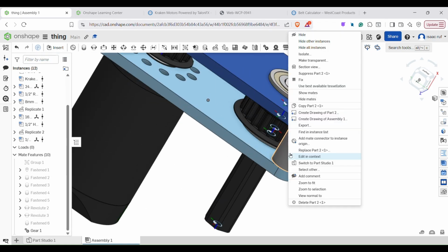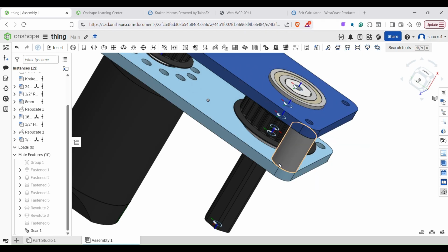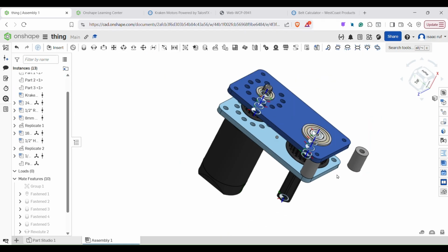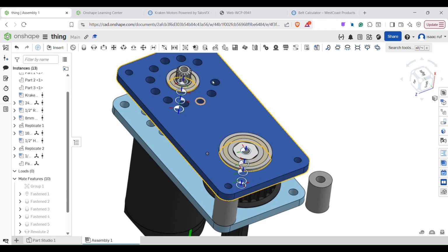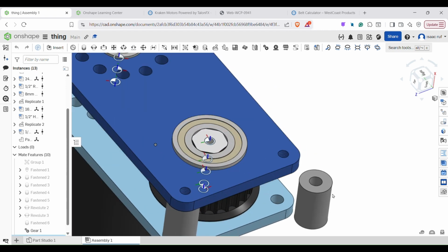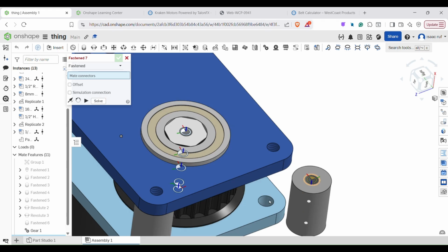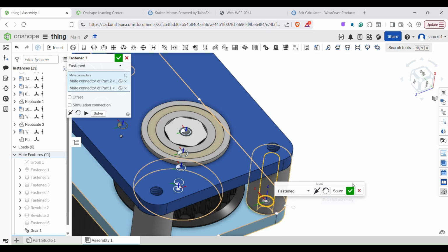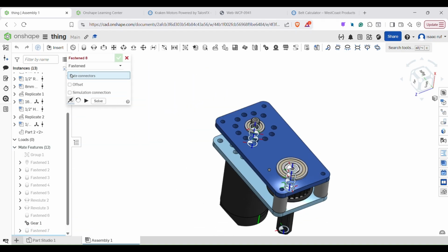And I'm going to take this, and we're going to hit Control C, Control V. Let's copy one in, and we're going to make it in there. Another thing we could do here too is we could put bolt heads in. I think I'll just do one to show you guys, and you guys could do the rest. You could use that replicate mate again. And I think I'm gonna use that here definitely because I don't want to do 2 more mates.